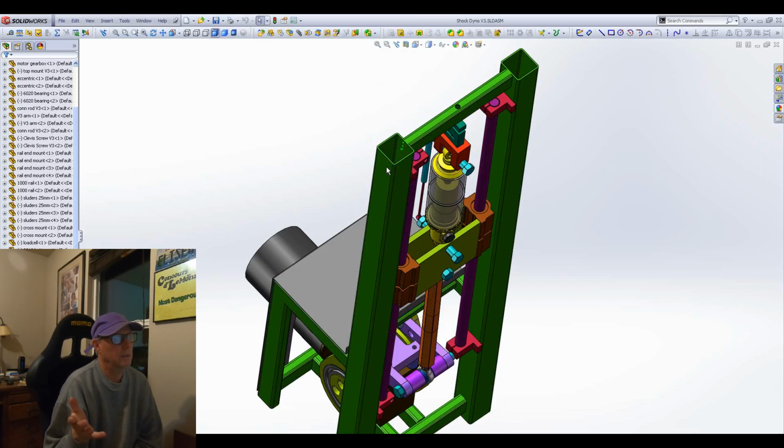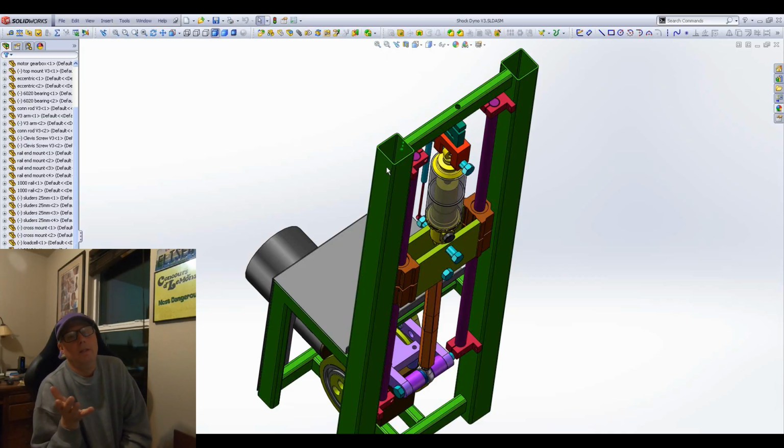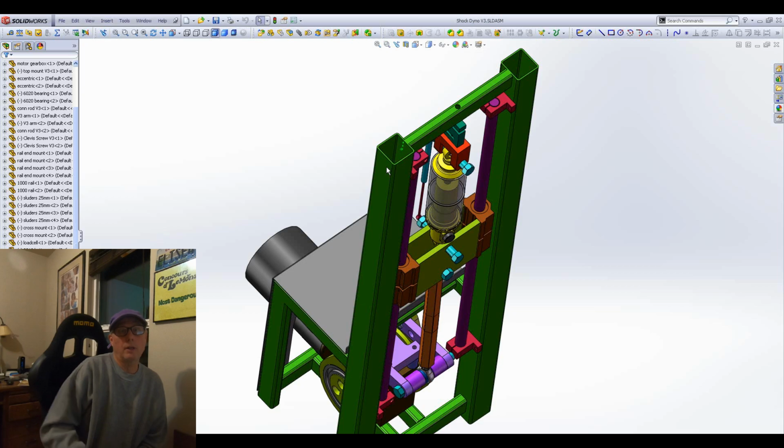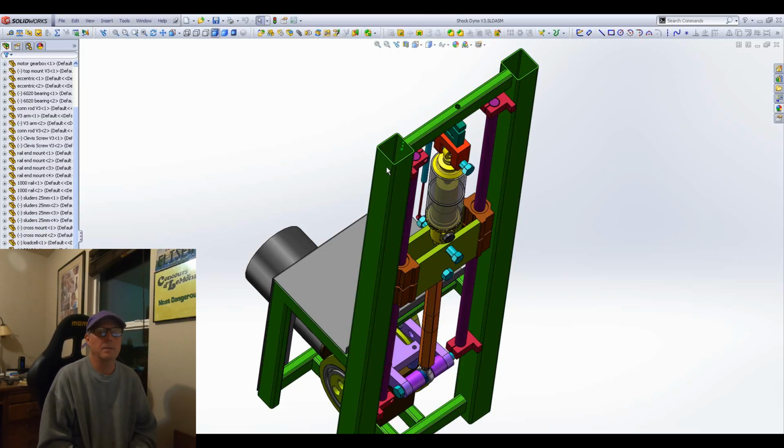Typically you want this structure to be as stiff as possible. The reason for that is, for a pull tester, if you want to take a sample and see how strong it is and pull it, you want to make that system really stiff. But that's not what people do. People make them thin, and then they look at the load and say, well, the stretch of the equipment is this much because we already calibrated it, and you just take that out. I don't like doing stuff like that.